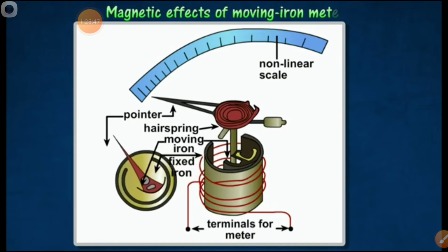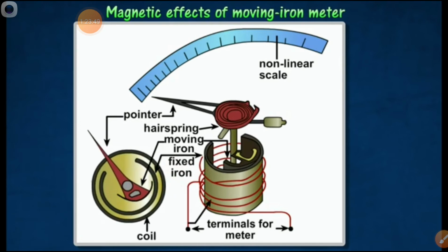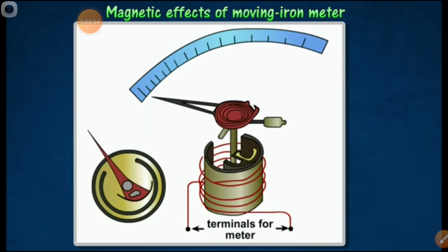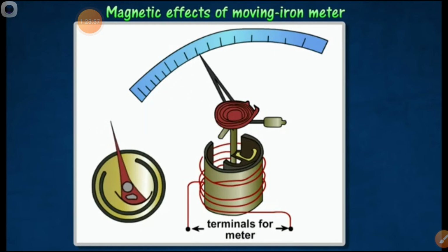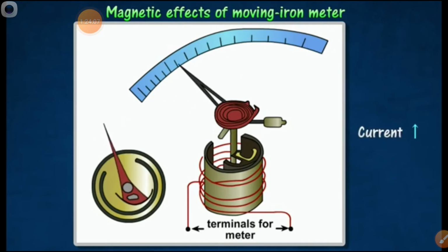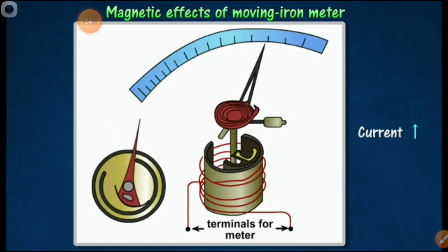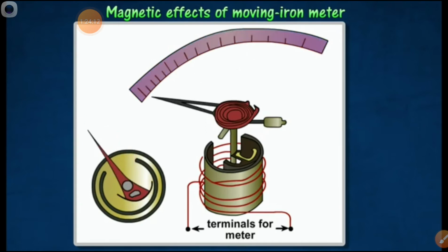Outside is the coil, and two vanes, one fixed and one moving, are attached. When the spindle moves, it moves the vane. When the controlling torque equals the deflecting torque, the spindle stops moving. It moves on a calibrated scale. A good animation, also courtesy to that person.